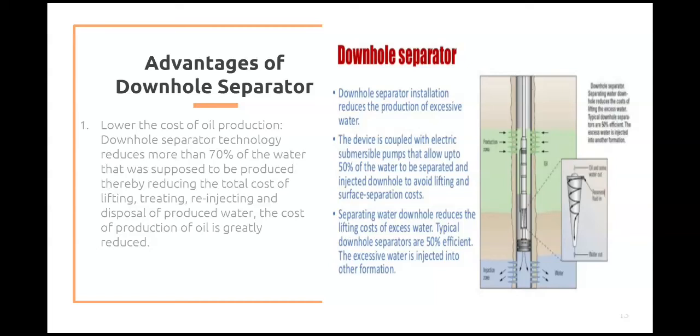First, as I said in the introduction, downhole separator technology will reduce the total cost of production of oil and gas. It reduces more than 70% of the water that was supposed to be produced, thereby reducing the total cost of lifting, treating, re-injecting, and disposing of produced water.